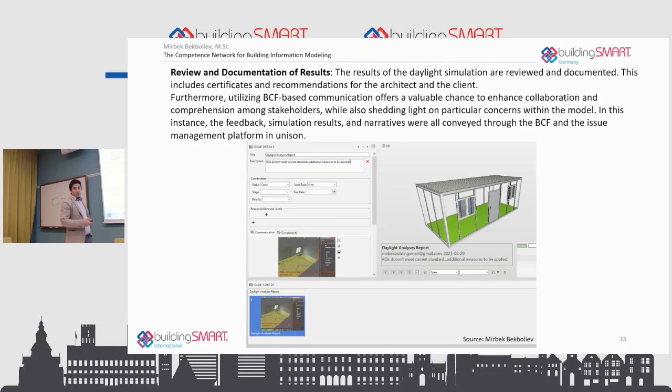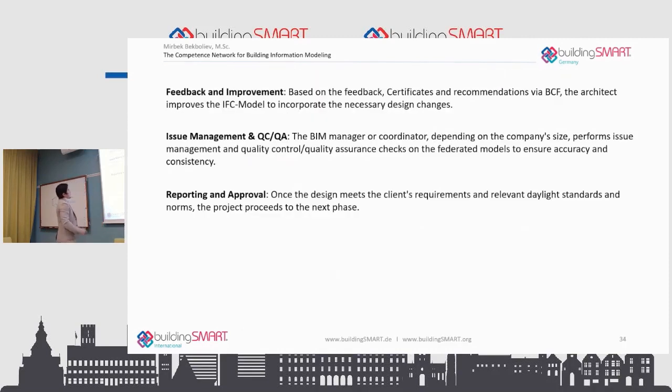In this case, I have a slab of the container. I simply selected that. I'm telling them I don't reach my daylighting goals with these windows and with this type of opening, so we need to have some solution. And I can write a small report and describe why. Plus, it happens on a model basis. It doesn't happen that you send an email. Of course, if you have an issue management platform, you can exchange BCFs directly over the platform. So the feedback you can send via the BCF, of course based on the model.